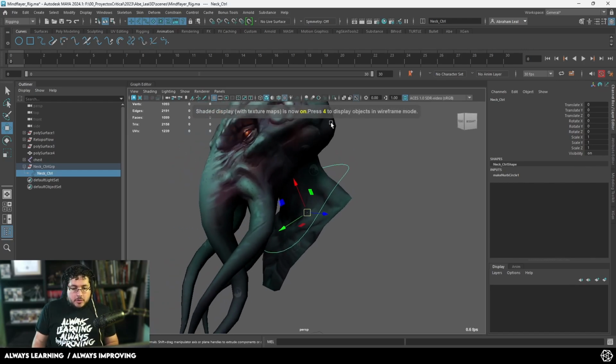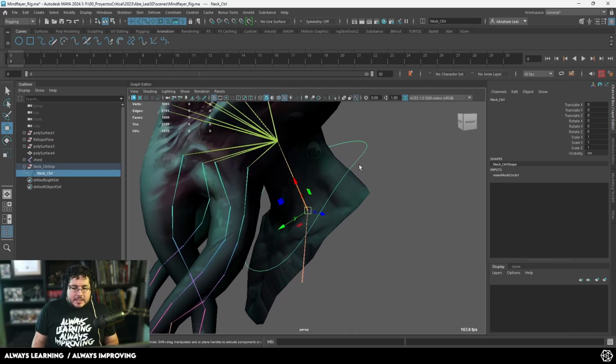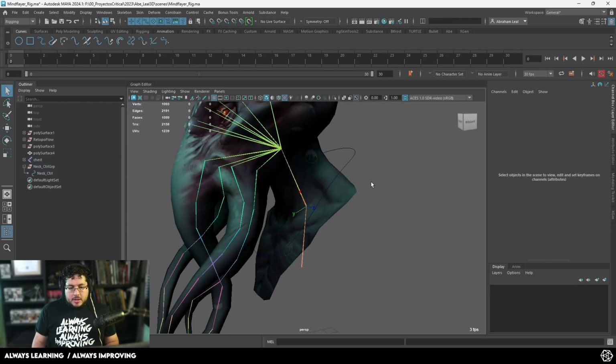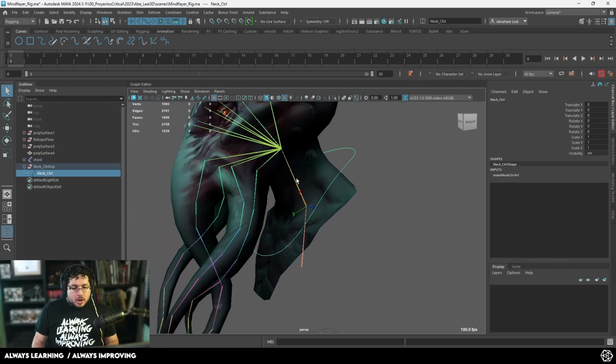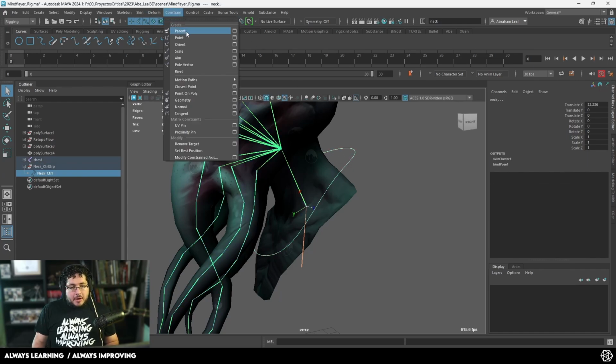Finally, the last step that we need to complete the process of attaching this curve to our skeleton is to create another constraint. Okay, so let me go here to show again. Let's do the viewport joints. There we go. So the last thing is I need to tell this curve right here that it's going to be controlling that joint right there. So again, driver, who calls the shots, and then driven, who's obeying those instructions, right? And we're going to connect the rotation and translation of this thing right here. So that means that we're going to be using a parent constraint.